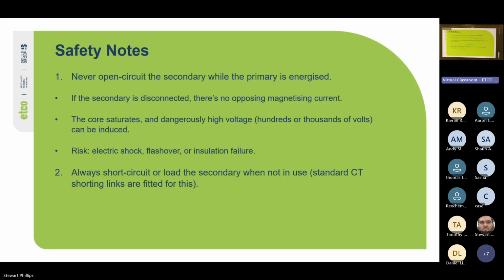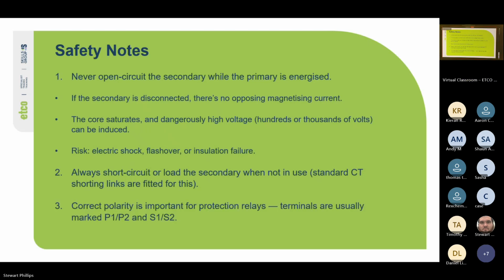Always short circuit or load the secondary when not in use. The standard CT shorting links are fitted for this. We must ensure correct polarity for protection relays. Terminals are usually marked P1, P2, and S1, S2.